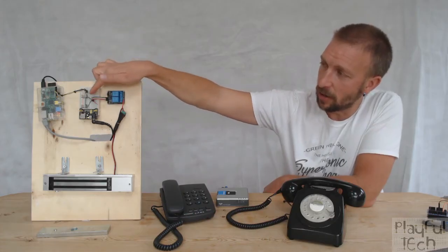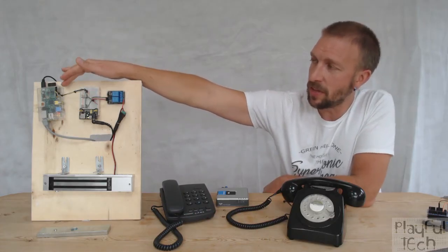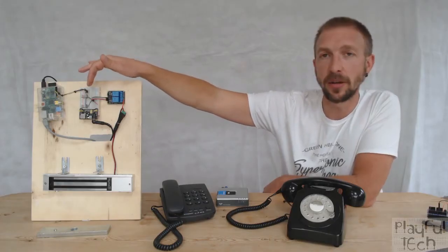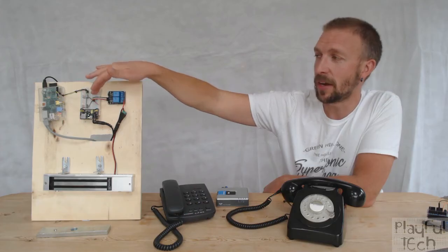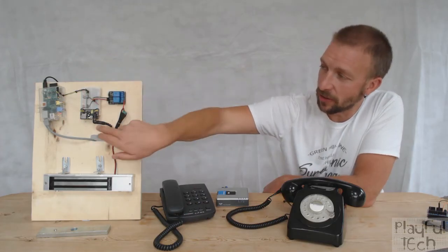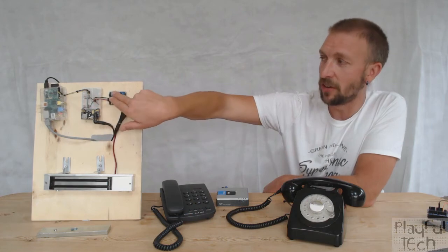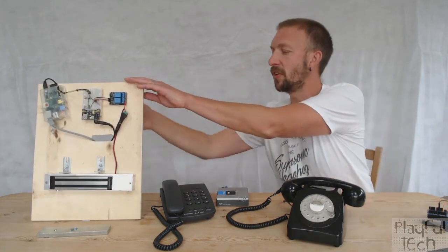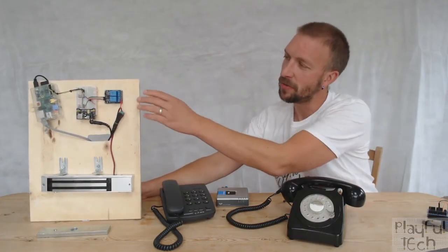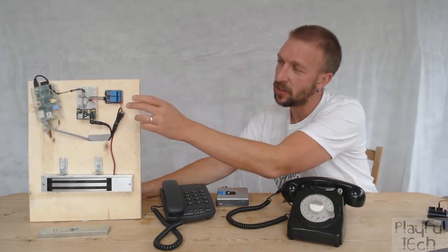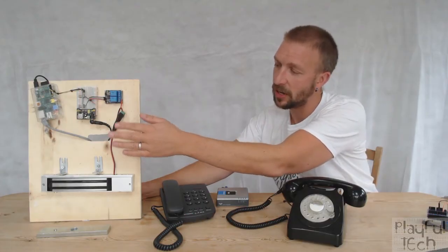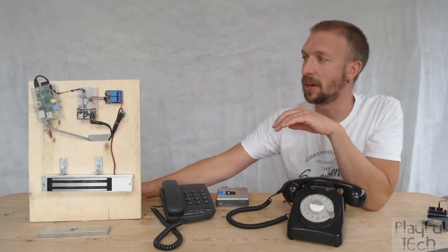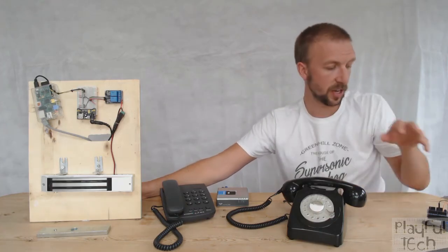What I've got here is a MOSFET, and when the Raspberry Pi sends a high signal here, which is 3.3 volts, that's going to activate the MOSFET, which is going to allow this 5 volt supply here to go to the relay. So this relay is running at 5 volts. So we've got the Raspberry Pi at 3.3 volts, the relay at 5 volts, and finally we've got a 12 volt supply here, which is going to go to the maglock. And so that's actually all the hardware involved.